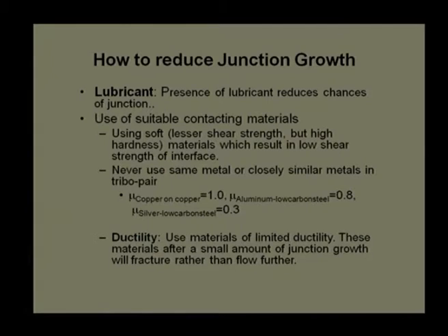Now, how to reduce the junction growth? I have noted down a few suggestions. Not necessarily everything will work in one situation, but one of the suggestions will work to reduce the junction growth. If you really want to reduce the junction growth, do not think about dry lubrication. Provide some sort of lubricant, either powder lubrication, solid lubrication, semi-solid lubrication, or liquid lubrication, which reduces the interface shear strength between two